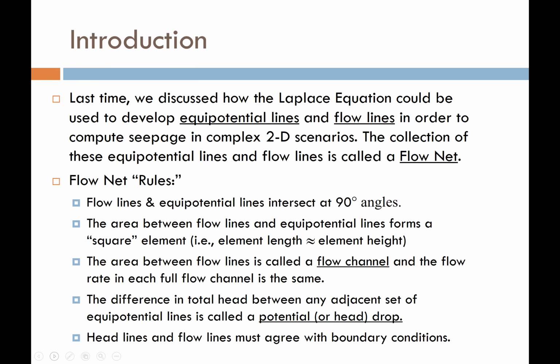So in the last lecture, we talked a little bit about continuity and derived the Laplace equation. And we showed how the Laplace equation could be pretty useful because we can solve for different piezometric heads or total heads at any x and y, or x and z, coordinate combination on a cross-section of a soil profile.